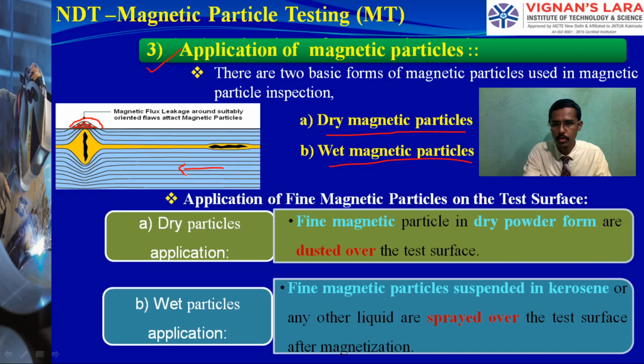If it is 100%, some fluctuations will happen, and with respect to that we understand the defect is available. One or two defects are given. See, this is the first one: a perpendicular defect, which is possible to detect with magnetic particle inspection.